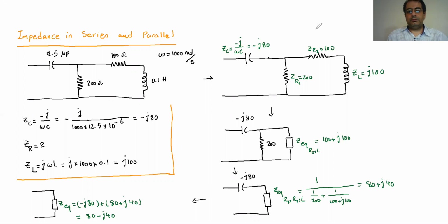So this is how we do that. If we have some elements together in the AC circuit and want to find the equivalent impedance, it goes like that. Convert the capacitance, the resistance, and inductance to impedance values. When you have the impedance values, simply assume they are all resistances and use whatever method we use for resistance to find the equivalent value, the equivalent impedance for that entire circuit, the way we did it here.